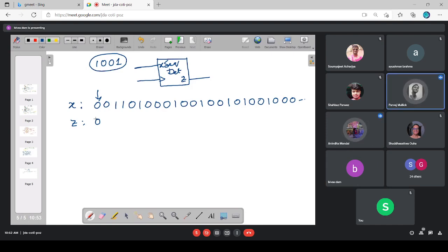No bit of the sequence has been detected. Fine. Then, first bit of the sequence. So at this rising edge, I am getting a 1. I know that my sequence starts with 1. So as the previously obtained bits were not part of the sequence, this may be the first bit of the sequence, but is the sequence complete? No, sir. So the output has to be 0. What about the next one here?